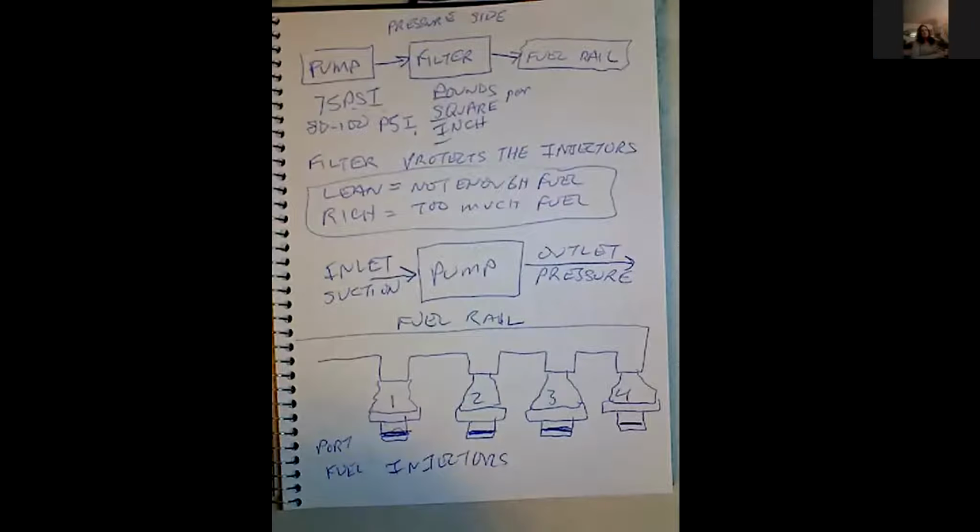Clearance is defined as the space between parts, the gap between two parts. We need space between two parts because when these things get hot, they're going to expand. They're going to get longer. So we need to make sure that the valve hits the seat because that's how it gets rid of the vast majority of its heat. If you don't get rid of that heat, it's going to burn the valve and then you're going to be very, very sad.